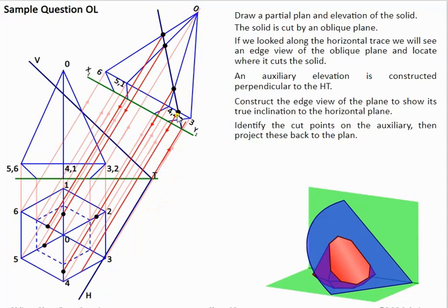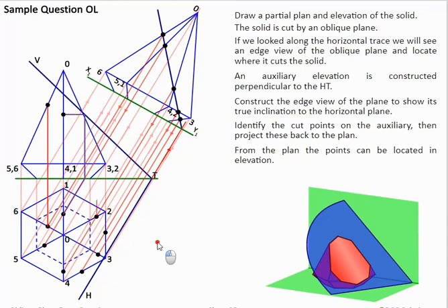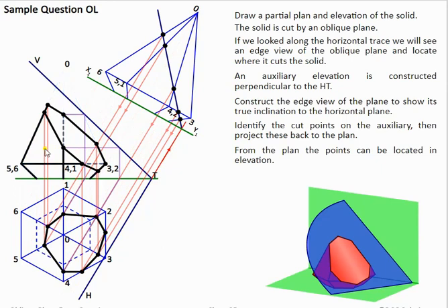Next we look at this point here. So looking at this, it is on the line 3,4 and 3,2, and then the final point is down the lower section here on the line 3 going down to the ground. So what we have is the full section now of all these points. We can join them all together in plan. Now we can bring them also up to elevation. Now we've completed in plan, we can complete the elevation and then draw in the rest of the elevation like this, and then complete the rest of the plan. So this here is what the whole shape looks like.